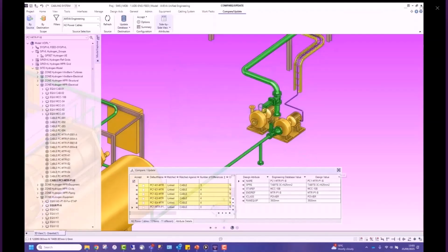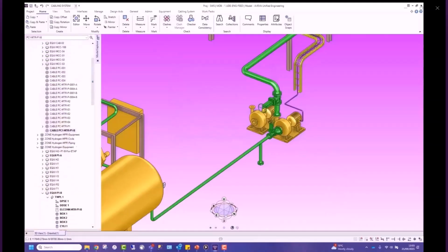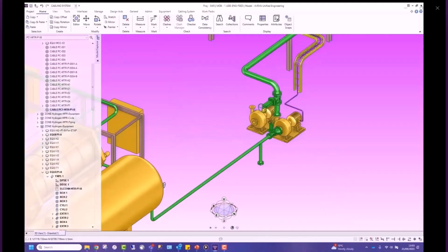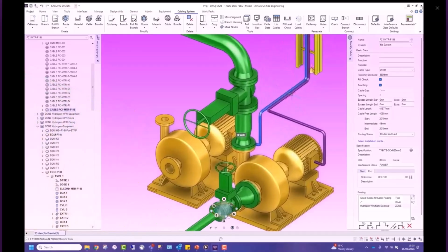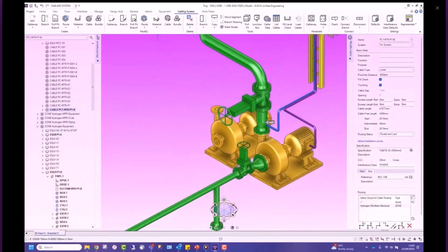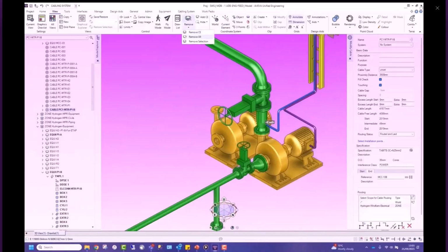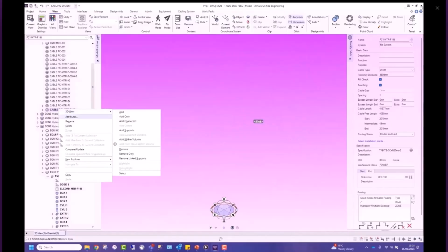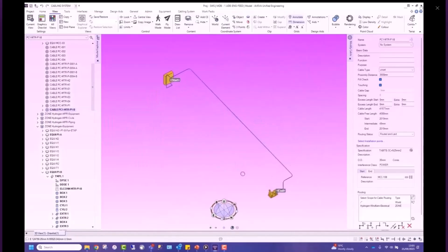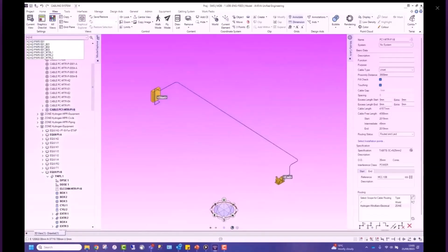The full cable spec, including connectivity details, are available from the master register, so we now use the automatic routing feature of the system to produce the shortest, clash-free route that utilizes the closest available cable trays. By isolating the graphical view to just the cable and associated equipment, we can clearly see the completed route in real-world coordinates. Full cable tray details are also available, including routing node details. They are now assigned to the cable and can be passed back to the master register.